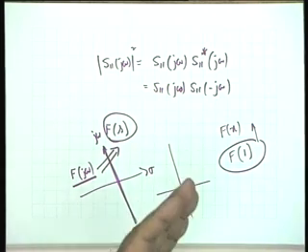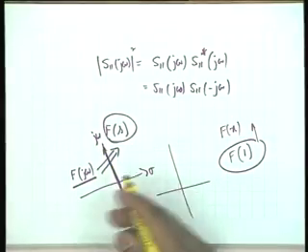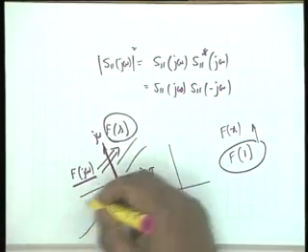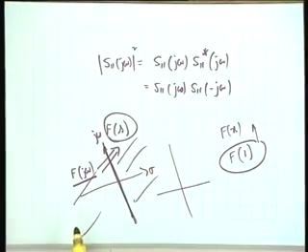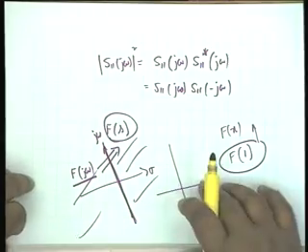maybe we have chosen only those networks. There are networks which do not behave so nicely. We are not concerned with them. We don't use them because we don't know how to use them. Here, fortunately, we can go from the j omega axis to the complete S plane, wherever you want, by simply substituting S for j omega. So, that is what we do.